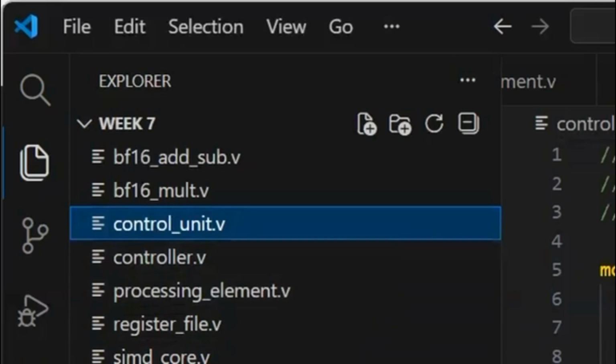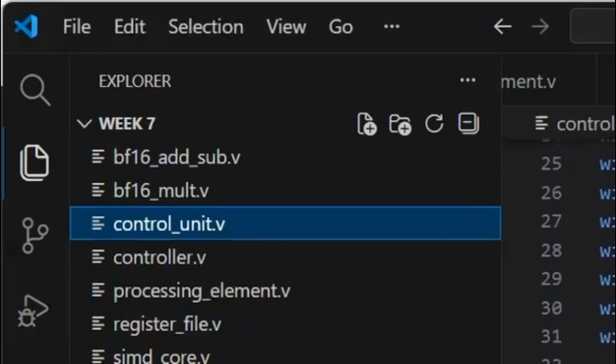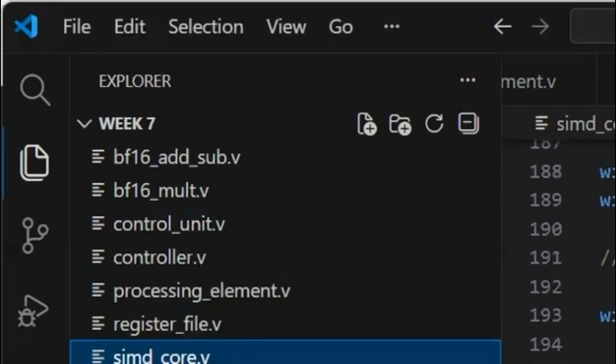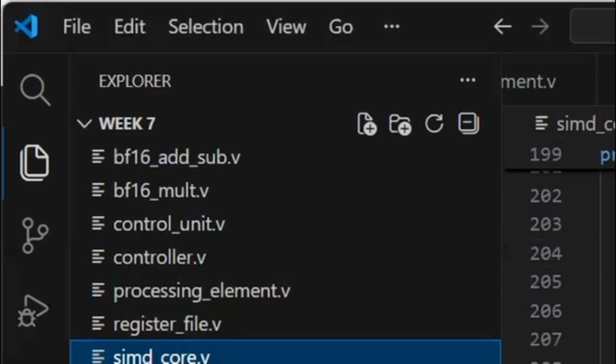And for the control unit, the instruction split will be based on the PTX ISA. We have developed an ISA which is compatible, and we also have a translator which converts the PTX into our ISA, where we can generate control signals based on that. Yeah, and this is the whole GPU. And now the tensor unit will be discussed by Siddharth.